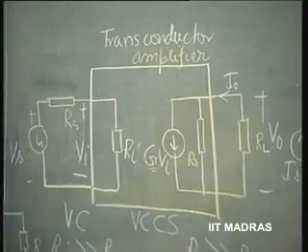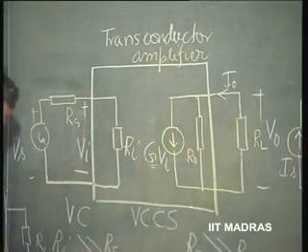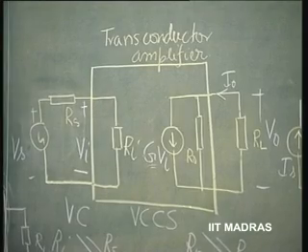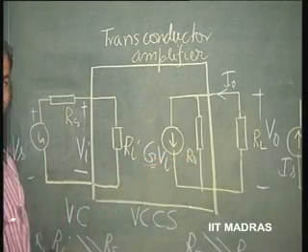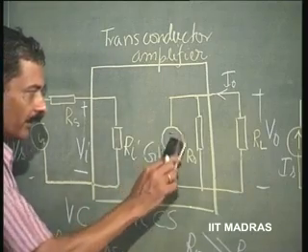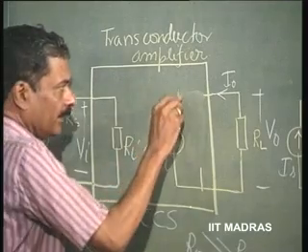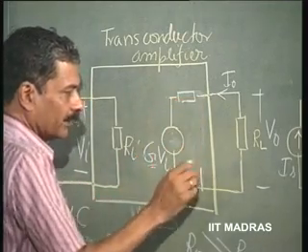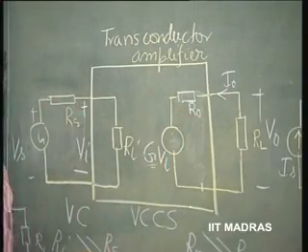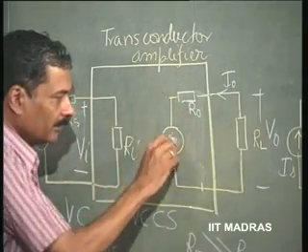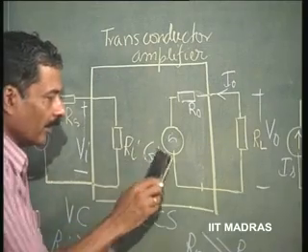Or if you think that this should be represented as a voltage source, you can represent this. So, I will make the alteration here. G times Vi shunted by R naught can be represented as a voltage source in series with the same resistance R naught. But this voltage is now going to be G times Vi into R naught.